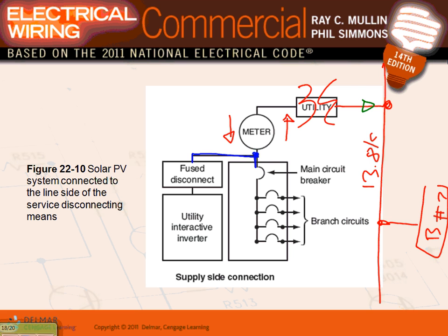If you have this system, the only limitation you have is how much your utility line can handle. So let's just put numbers here. Let's suppose that this was 2000 amp, 480 volt, three phase obviously, and I'm going to have my fuse disconnect system here as rated also. Let me say I'm going to generate 2000 amp, the same thing, 480 volt, three phase.